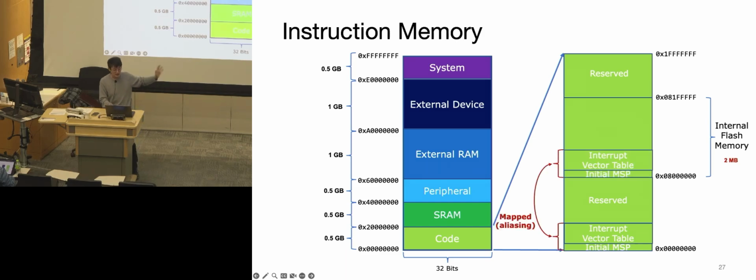In the lab, just for some clarification, sometimes they will make aliases. Basically, they copy those over to a different address, like 8000000, where the flash starts. This is because if you want to store your code for the long term, you should put things there, because whenever the power goes off, the code is still saved there, and whenever it boots up, the system will automatically run the same program over.